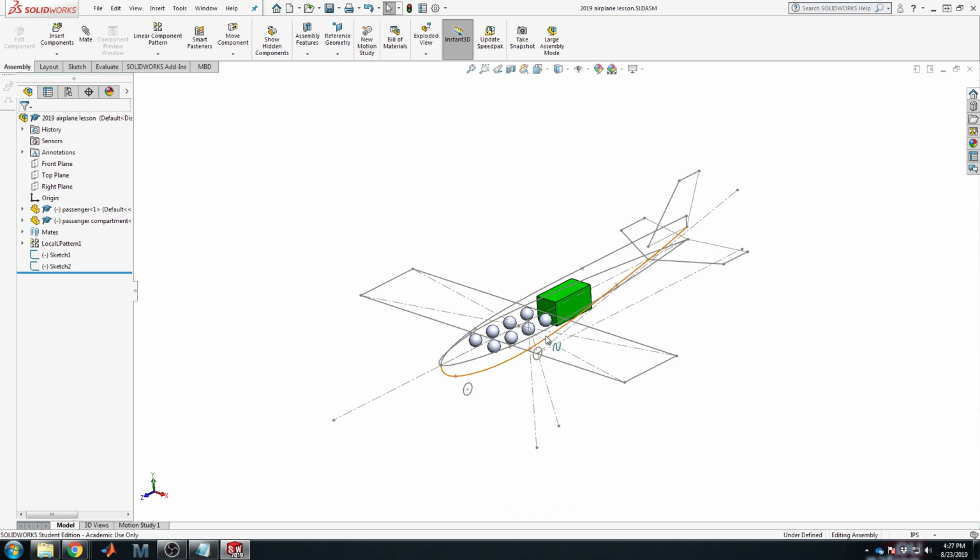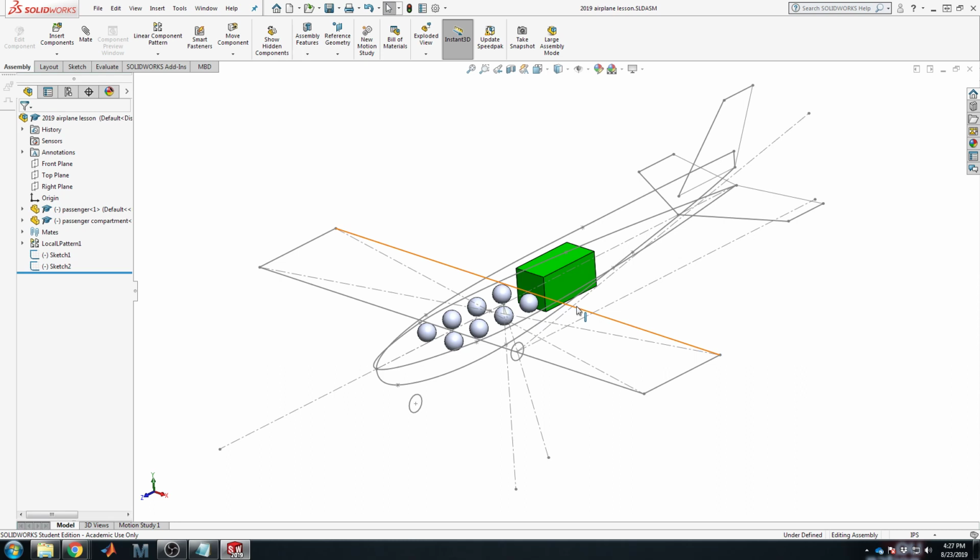And again, just as a reminder, you should lay out your systems, meaning servos and batteries and whatever other payloads or receivers, electronics, everything system-wise should be here. That is going to dictate the geometry of your plane. Do you need to model every wire at this point? No, definitely not. Do you need to model little control rods? Probably not. But anything that's bulky, big, you have to fit into the airplane and fit around would be advisable.